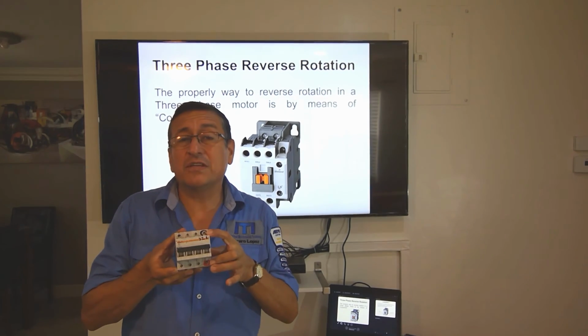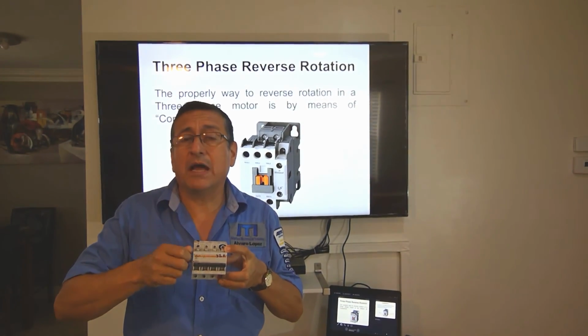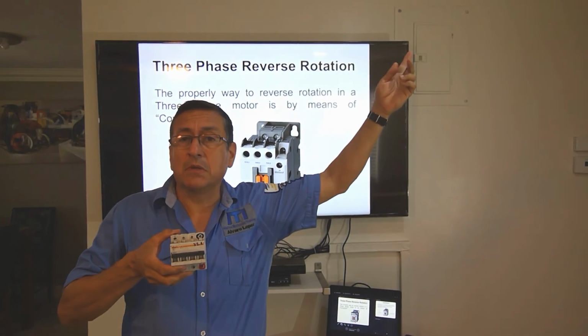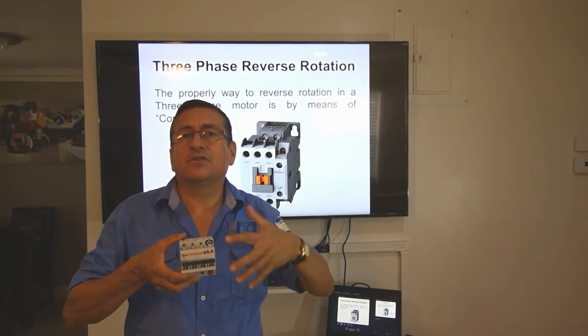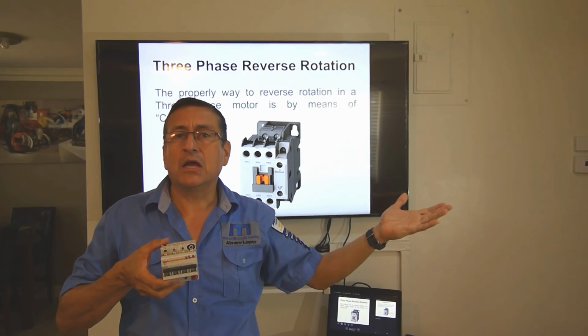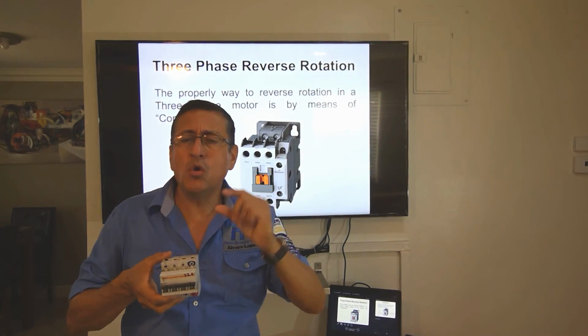What is the function of the signal? Open and close the breaker. Where is that signal coming from? It's a remote signal. That signal, once again, is coming from the flybridge, from the pilot helm, and it could be a DC signal or an AC signal, low current signals.